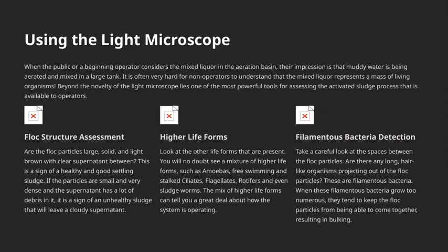Next, observe the other life forms present in the sample. You'll likely see a variety of higher life forms like amoebas, free-swimming ciliates, stalked ciliates, flagellates, rotifers, and even sludge worms.